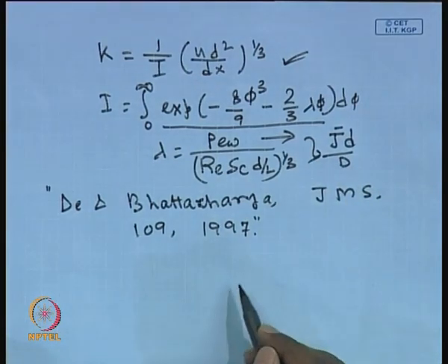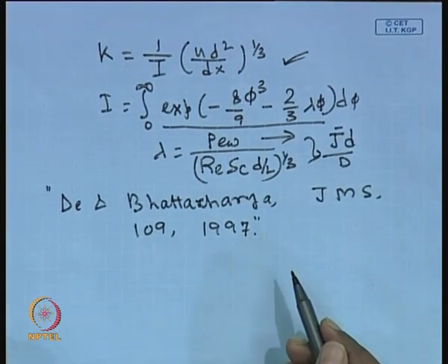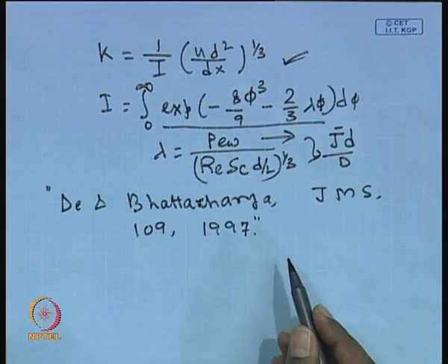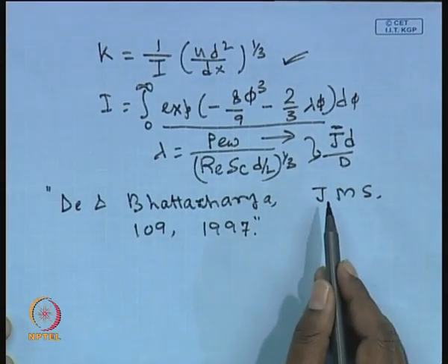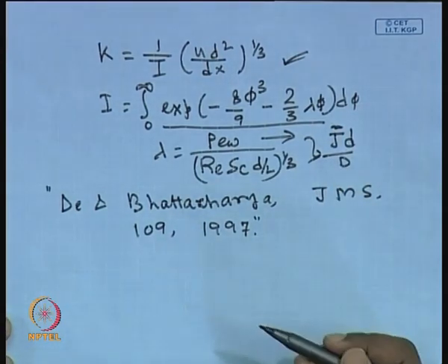Now, again the algorithm that we have discussed in the last class will still hold good in this class as well. We will be assuming a value of length average permeate flux, and then we will solve 3 ordinary differential equations coupled with one algebraic equation that has to be solved iteratively at every step of the Runge-Kutta 4 algorithm for the solution of ordinary differential equations.